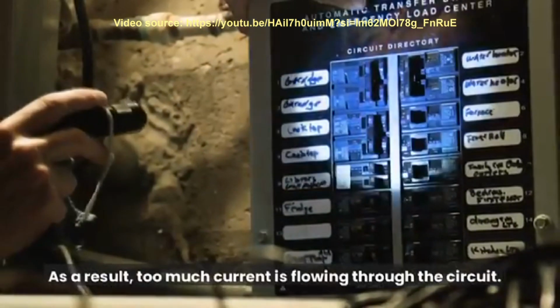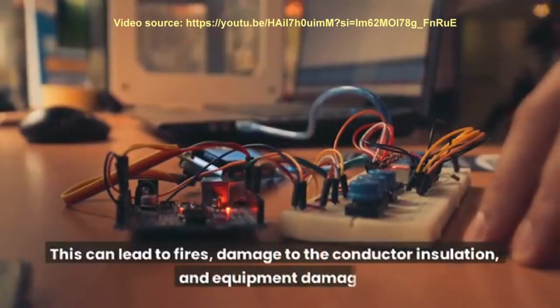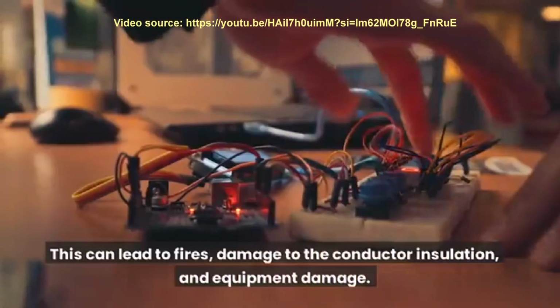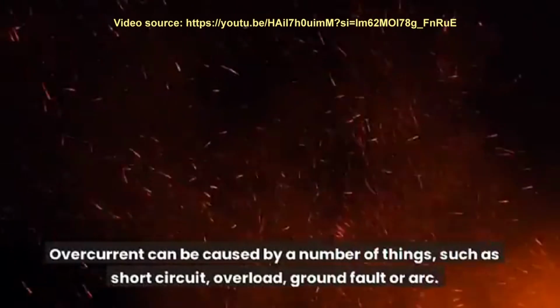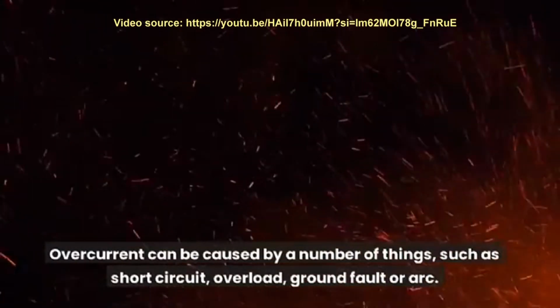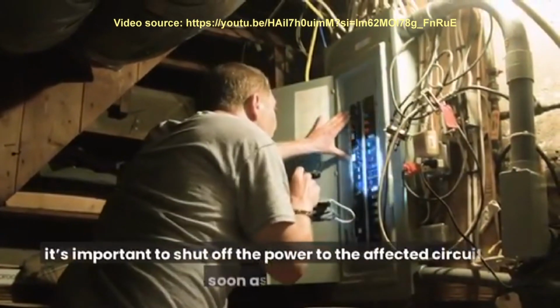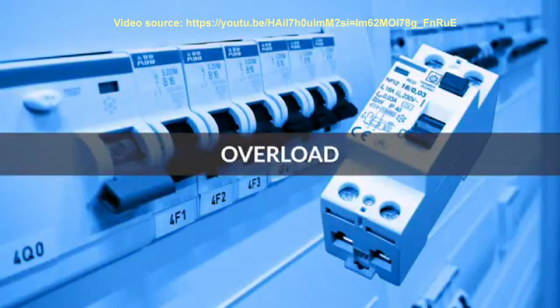Overcurrent. Overcurrent is a condition of an electrical circuit when it exceeds the maximum current allowed. As a result, too much current is flowing through the circuit. This can lead to fires, damage to the conductor insulation, and equipment damage. Overcurrent can be caused by a number of things, such as short circuit, overload, ground fault or arc. Due to the potential damage caused by an overcurrent, it's important to shut off the power to the affected circuit as soon as possible.